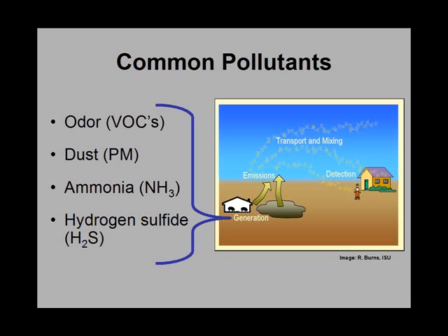So what odor actually is, is a really incredibly complex mingling of over 400 different chemicals that collectively are known as volatile organic compounds. And these chemicals come about through the anaerobic decomposition of manure. And these chemicals attach themselves to dust. And to a high degree, as odor moves across the landscape and reaches people downwind, it's dust-borne odor. So it's all of these VOCs collected on the dust that move downwind, and it's detected by people.